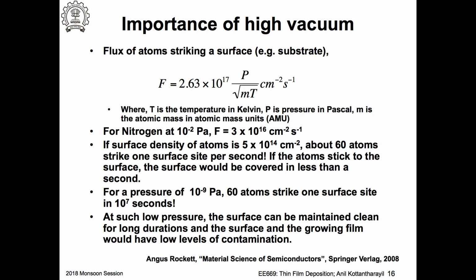So this is a very important consideration, because this is why when you do semiconductor processing, you clean the surface. Very important. If I want to grow, let's say, a very high quality oxide, the surface has to be cleaned. But then I take this wafer out and I'm walking in the clean room with this. You know what is happening, right? If I am looking at very good quality interfaces and so on and so forth.